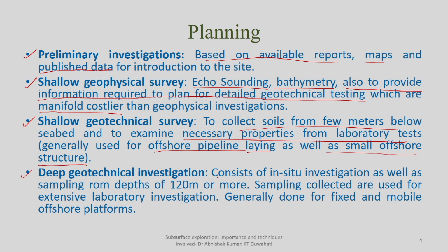So, it consists of in situ investigation, because everything has to be done in situ. Nowadays when we go for geotechnical investigation, there are two ways: either you can do the testing from the vessel itself, or you can lower down your testing assembly at the sea floor, and from there onward you can start your drilling, sampling and testing everything from sea floor itself. So, the entire operation can be controlled from the surface vessel or control unit by means of cables or other medium, or you can do the testing from the vessel itself. So, both options are available, which people are practicing nowadays.